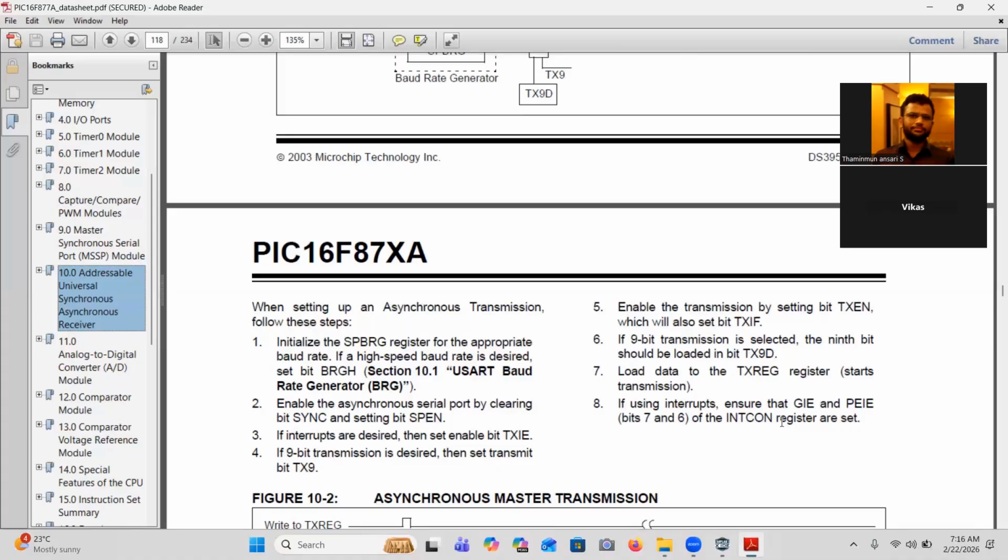Let's say when the head of the ECE department wants to communicate something, that is only applicable to that department. It is not applicable to other departments. Yes, no? In a similar way, the global interrupt enable is a control for all interrupts that we have in the microcontroller. When you disable that, even if you have peripheral interrupt enable, that doesn't have any value.